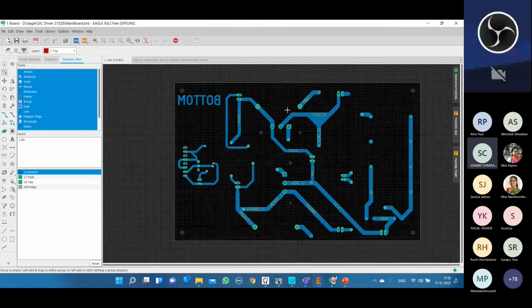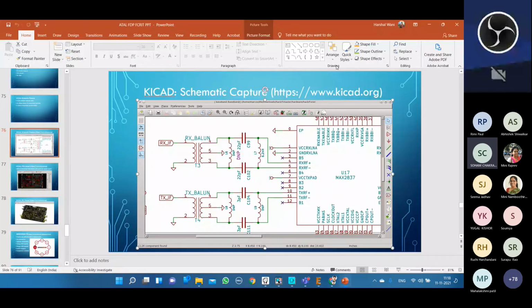This is the PCB that I had designed. So there you will get such kind of option. You make the PCB schematic there, and then switch to the board. But as a general instruction to all of you, whenever you make this schematic, be sure that a footprint is available for that schematic. Okay, make sure that footprint is available for the schematic.